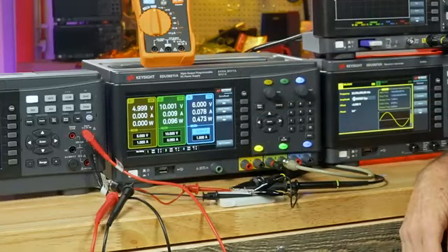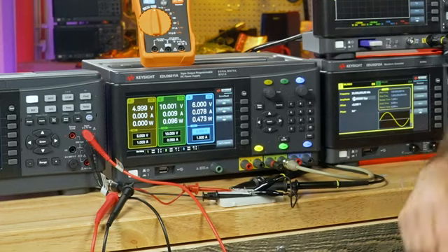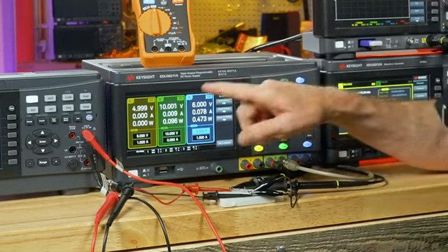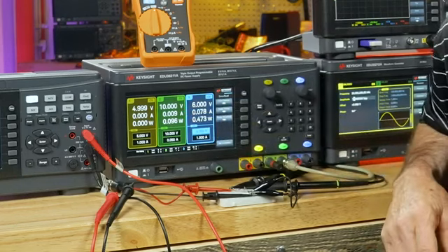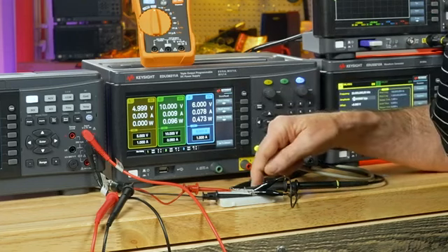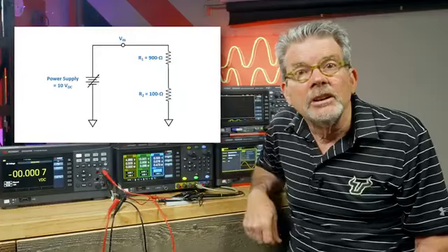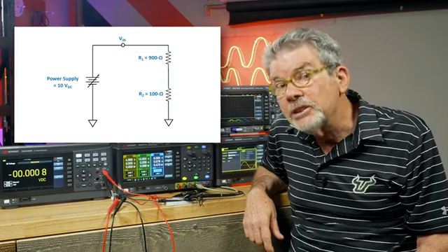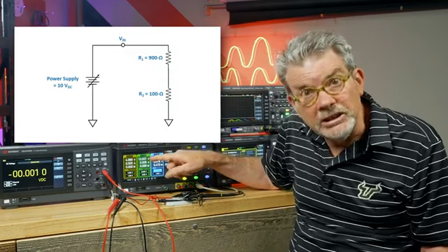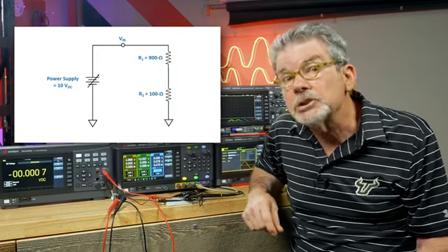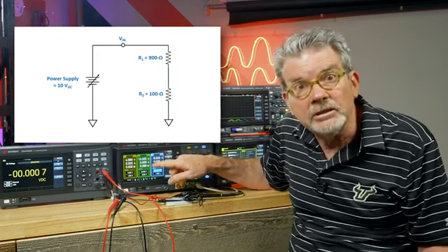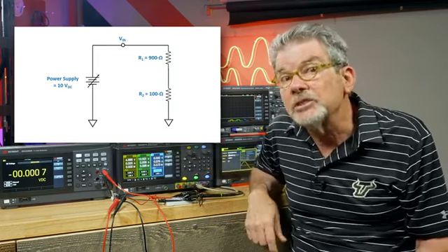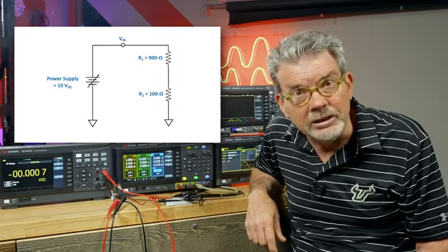As you can see here, I've got channel 2 output of this power supply set to 10 volts and is powering up a simple resistive divider circuit. When the DC power supply is connected to a circuit, besides showing the fixed DC output level, it also shows you the amount of current that is being drawn as well as the amount of power that is being delivered.